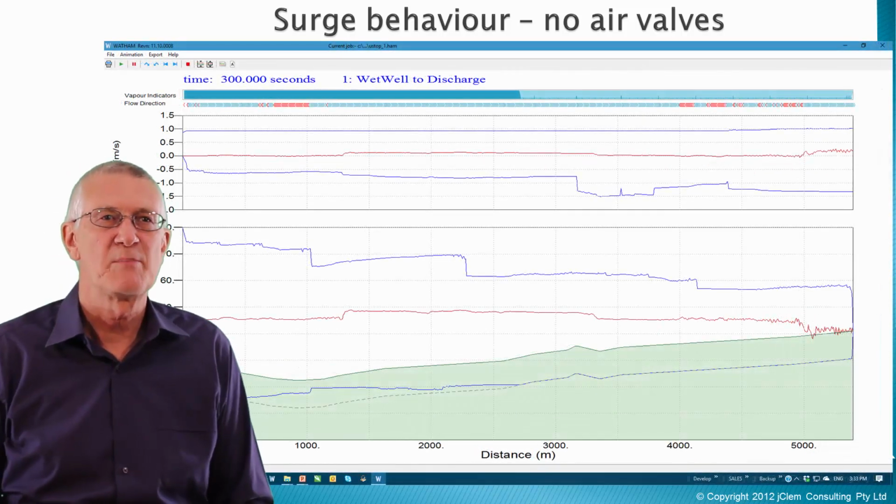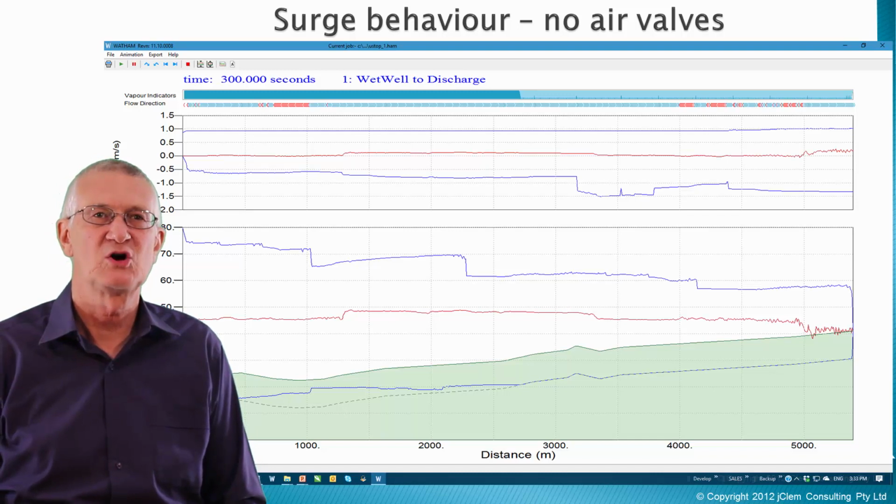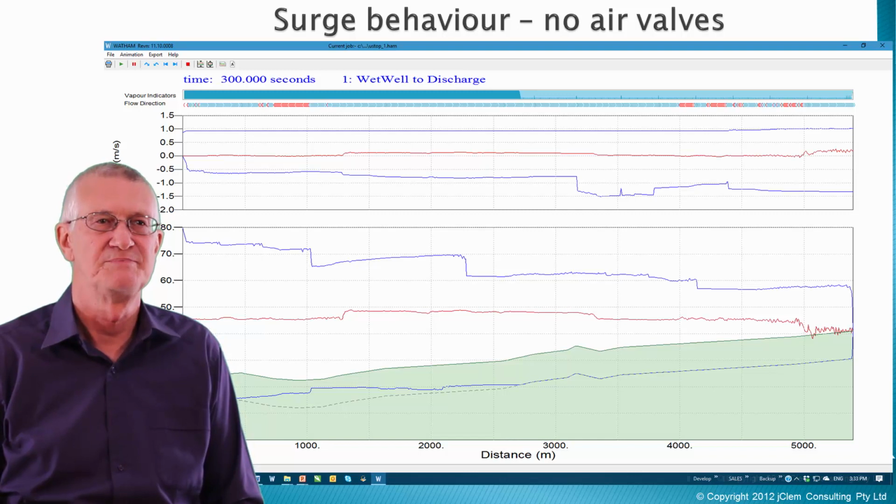Okay, we saw how pump stop affected head and velocity as a pipeline long section. And in the interest of time, that presentation ended at about 28 seconds into the simulation. Beyond that time, the reflecting wave progressively increases head and returns various portions of the pipeline into the fluid phase. In time, the whole content of the pipeline will come to rest, yet not under our control.